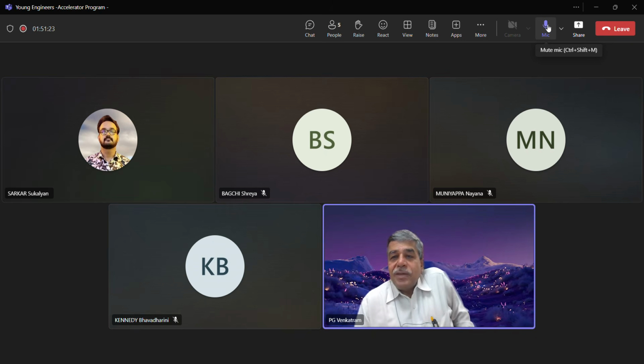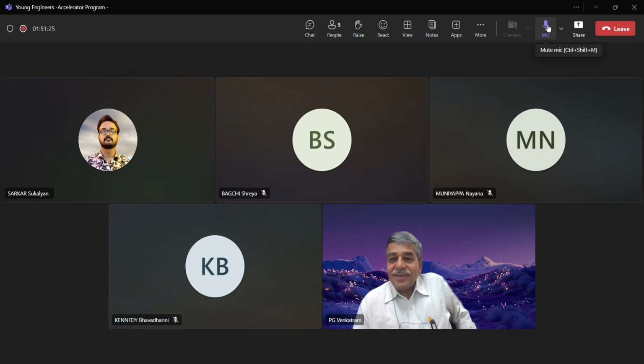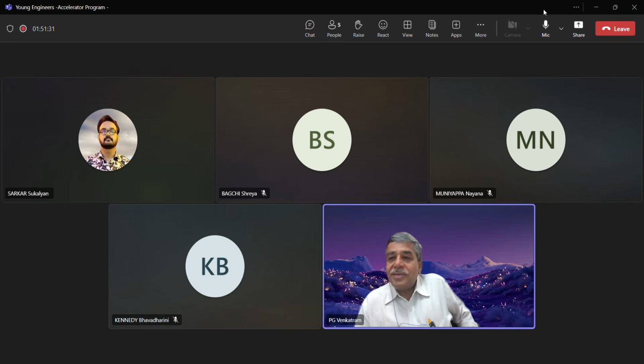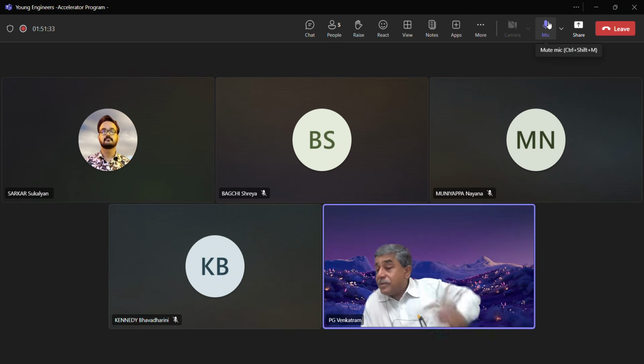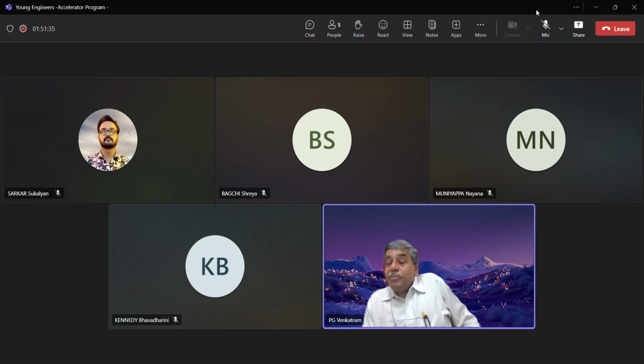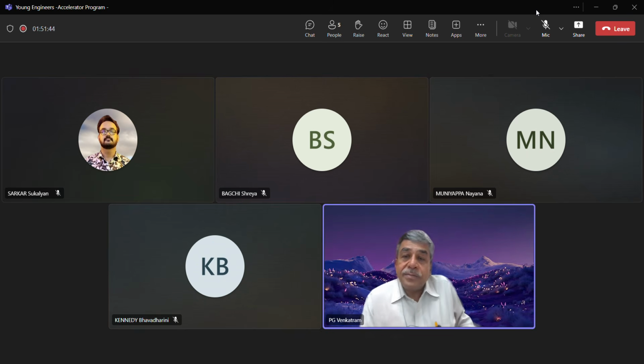Unless you show me a photograph, then maybe I can give you an input. That is possible. Weak pedestals have been reinforced by confining with steel plates all around and grouted and filled. That I have seen done.